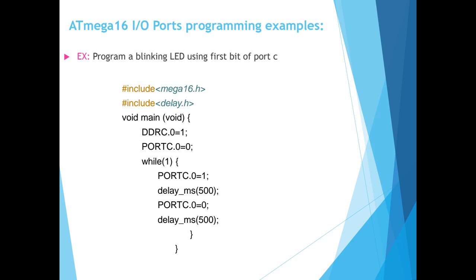No, I mean, we don't want to read its data. We want to interface with a device, with the LED. It should be configured as output. The index is starting with which number? Do you remember, for the first bit, we should use 0 or 1? I explained about it. The index is starting from 0. So at first we need to configure it as output.